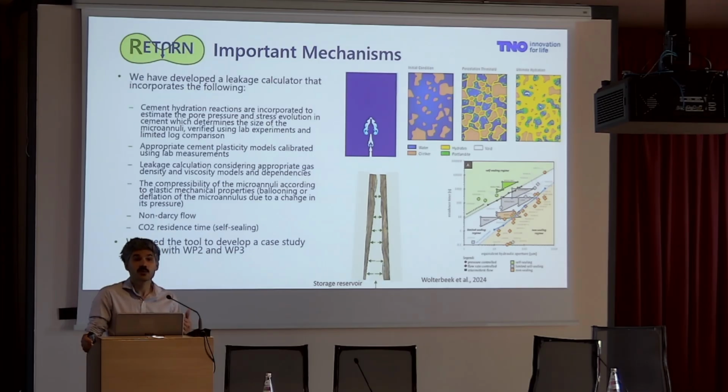And we argue that we want to use mechanistic, physics-based models, by coupling geomechanics and well leakage, to understand when these defects will actually open. In fact, they're quite dynamic. They're not always open or closed. They do open and close as you operate your well. And then you have your pathway, but at the end of the day, you also still need a pressure gradient to be able to leak out of your system. So the combination of these would give an indication of whether your well is going to leak, how much, over what period of time.